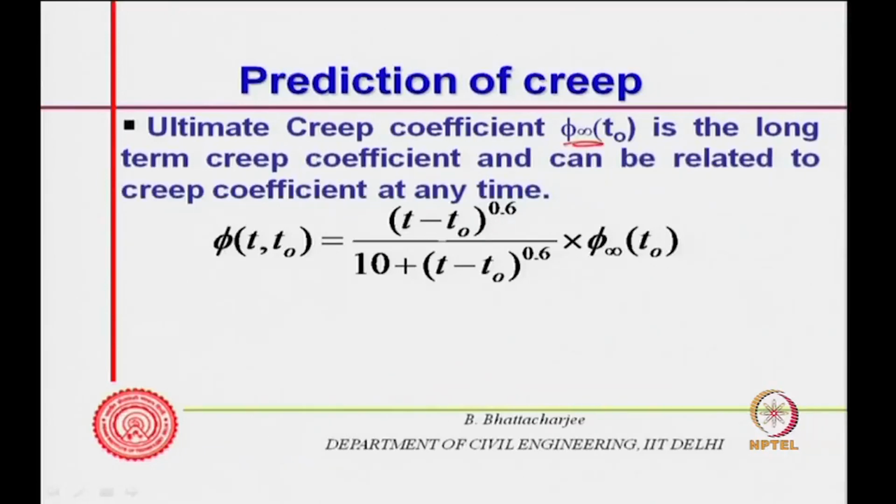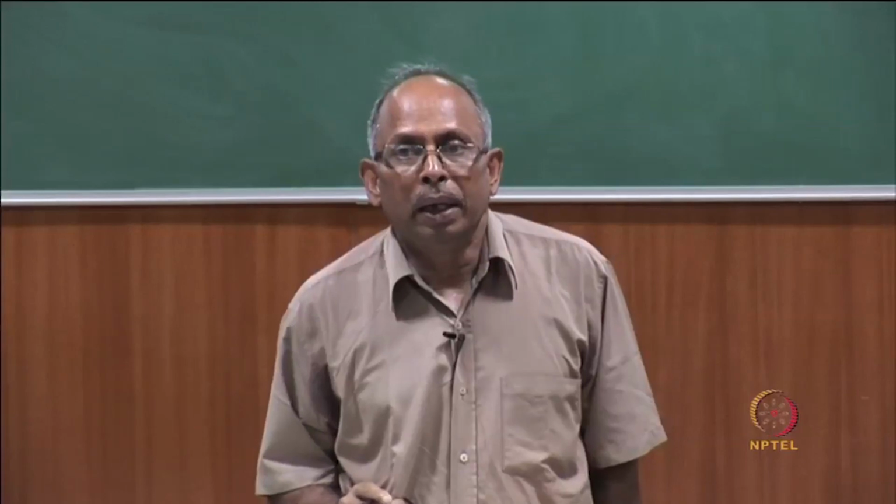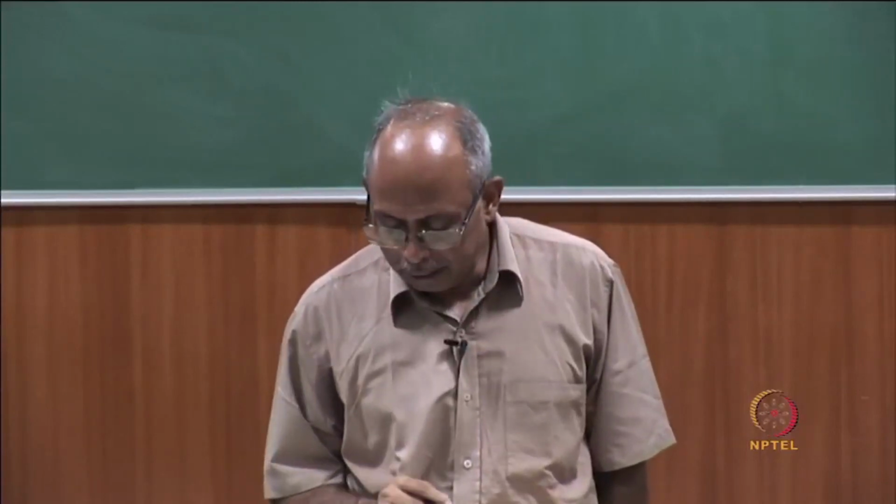This is an empirical formula, and that is the ACI guideline. Here t0 is the time of application of the load, and t is the time at which you are finding the creep coefficient.